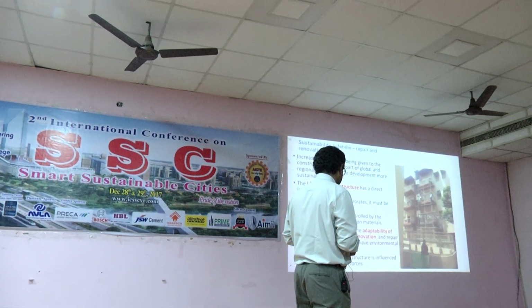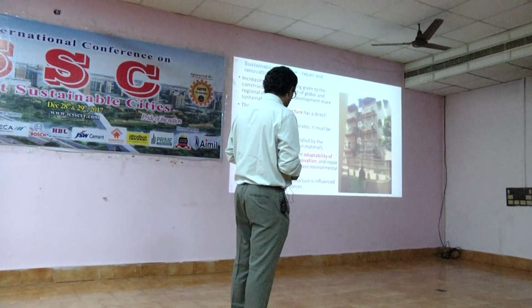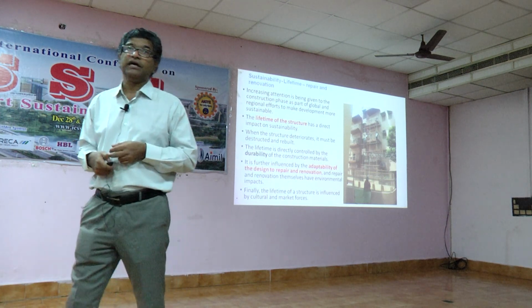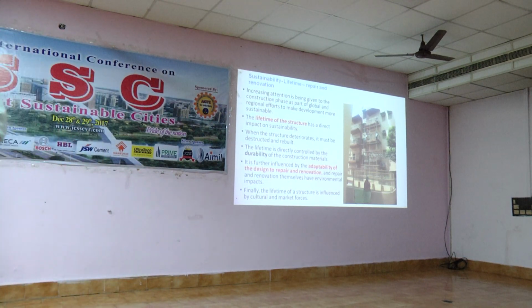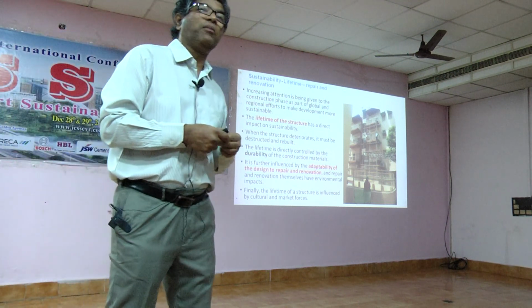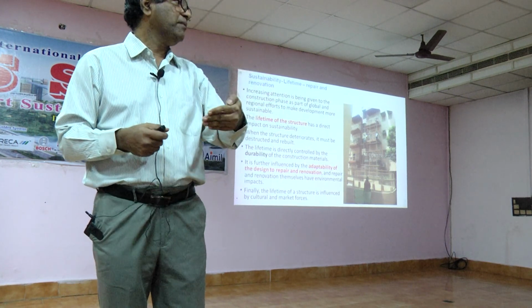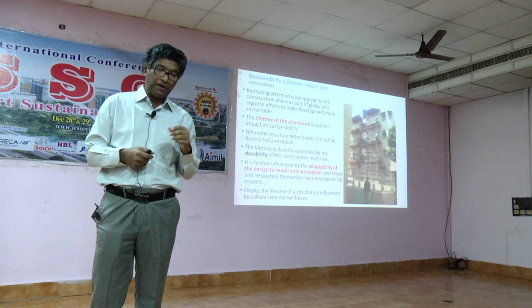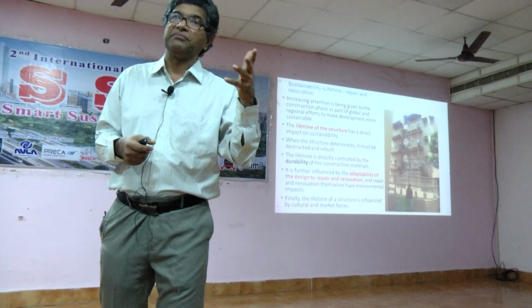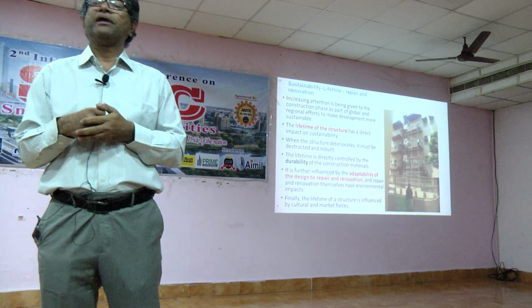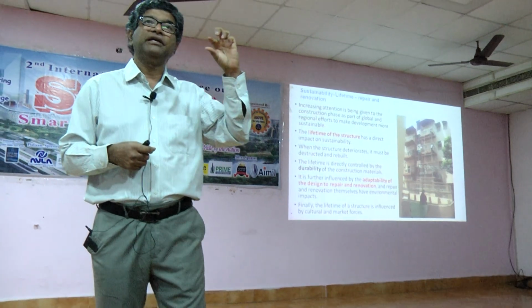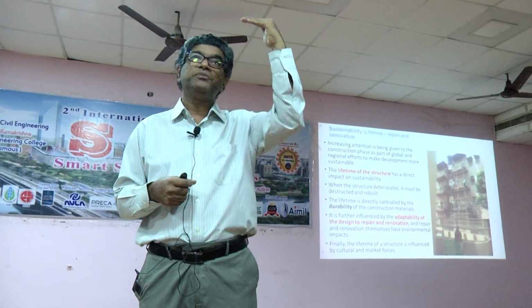And the adaptability of the design to repair and renovation. Whether it is an architect or a structural engineer, both of them have to sit together and understand what sort of material they are trying to use and what the lifetime of this product is. Nowadays I am seeing architects using so many products coming into the market, like certain facade elements from Germany and other places, manufactured with waste paper. They compress the paper, add some more elements and make a thin element of about 6 to 10 millimeters, which is used for facade.